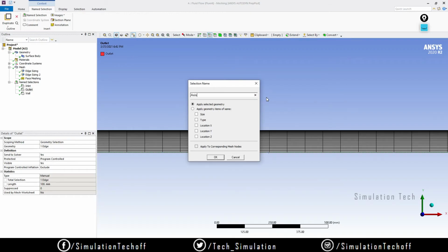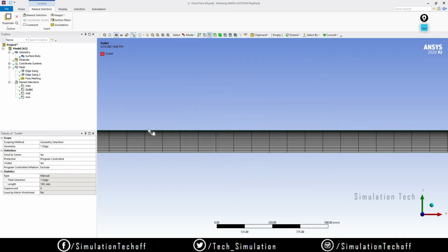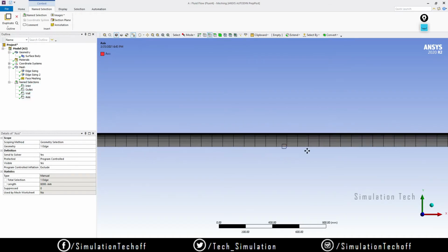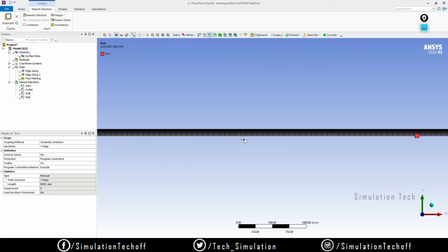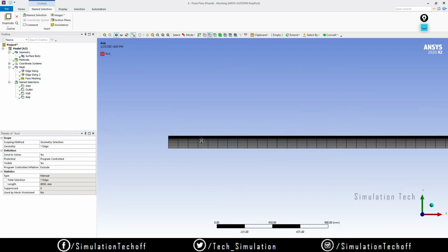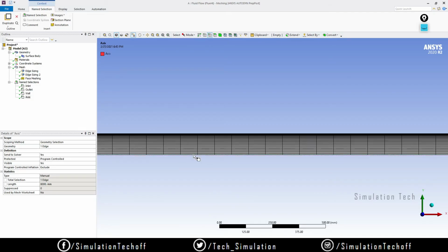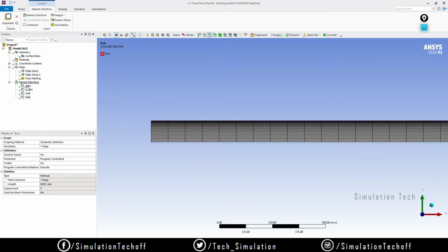So when we get into the Fluent environment, just make sure whatever name you may give, such as inlet velocity, outlet, wall 1 or 2 or 3, you should always use that keyword. Otherwise you need to manually assign everything. It may be a complicated process when we are in Fluent. So I think we completed the creation of the meshing part and the named selections.